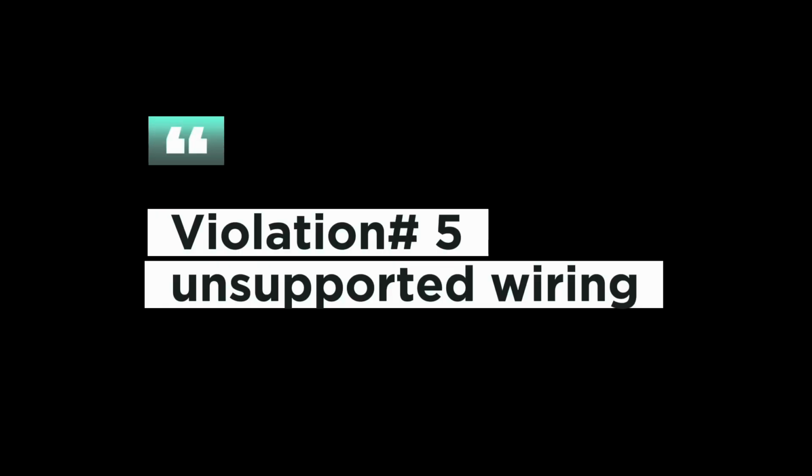It is important to really connect the ground, to realize the connection of the ground. It's important to ground all the control panels when it is required. There is no reason to not do it because it's a protection. When an equipment is grounded, it means that all leakage current will be redirected directly to the ground.